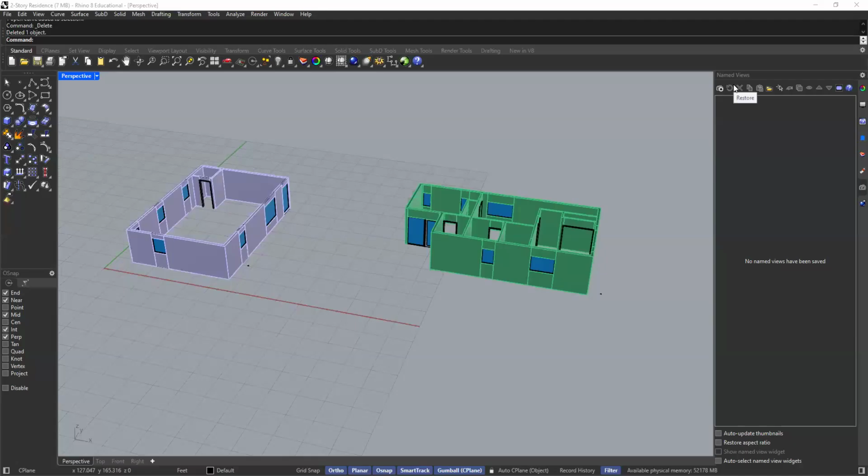So in this tutorial, I'm going to cover how to create the roofs. I'm going to break this up into two tutorials. One is just covering how to do a typical hip roof. This is where all of the roof panels or roof sides are all kind of angling inward. That's known as a hip roof. And we're going to use a 3:12 ratio to create the hip roof over the second floor plan.